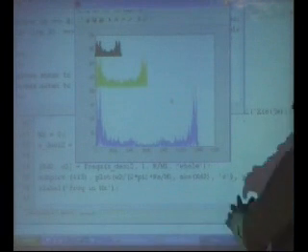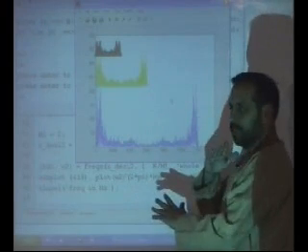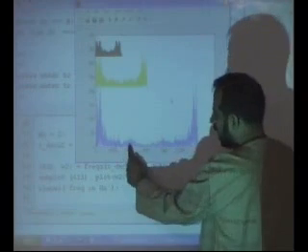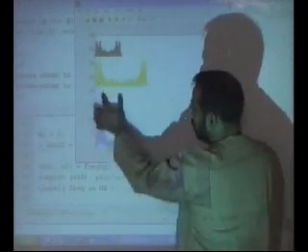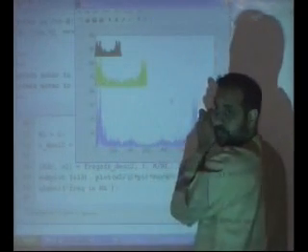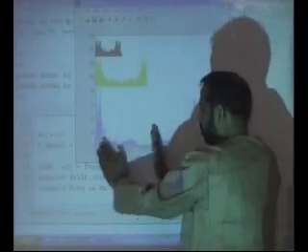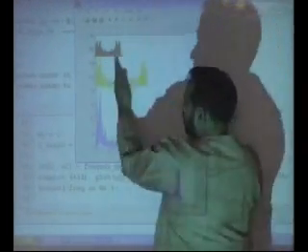But remember, doing this, you have not passed it through a filter. Ideally you must first pass it through a filter. If you really want to do it, clean half of the spectrum, and then move it so that this part should not go and corrupt this part. Preferably you do this, but here I've not done that. I'm saying cut it down, throw away, and then again if you do this, what is meant by that? That you cut it down from here.